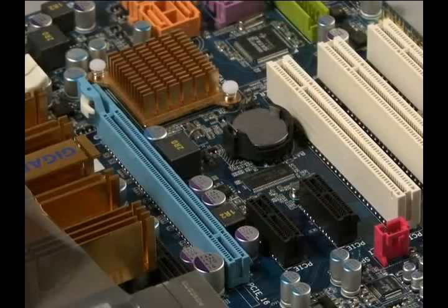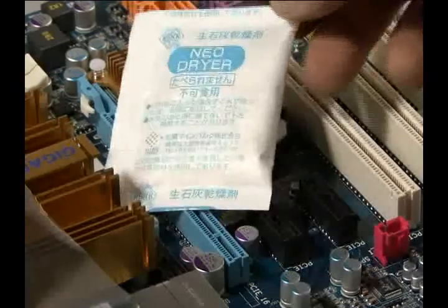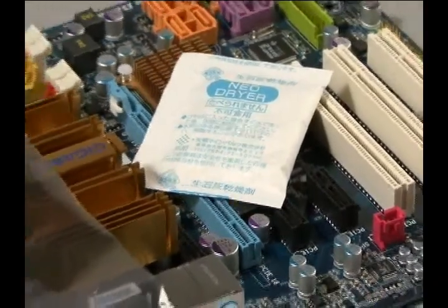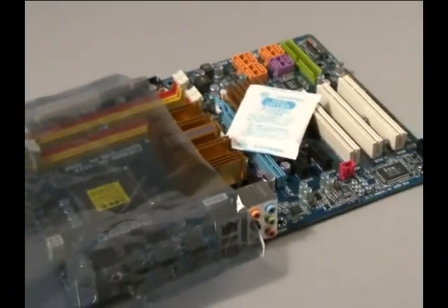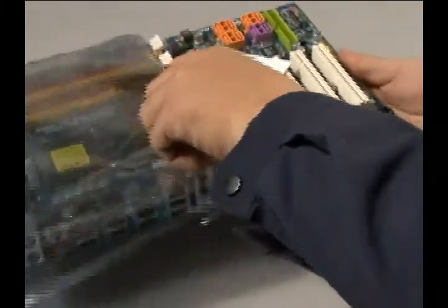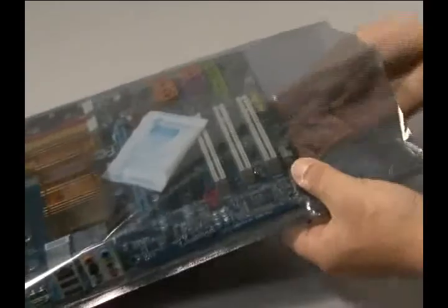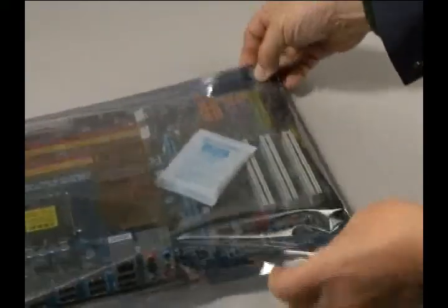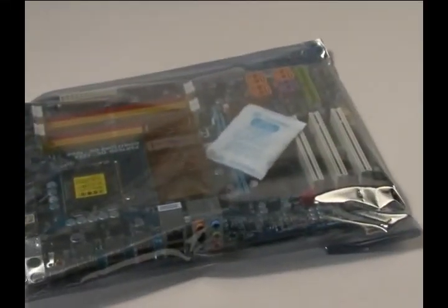A spare electronic circuit board is provided on board ships in case the board in use breaks. This spare electronic circuit board must be placed in a cool place to ensure that it can be used over an extended period of time. However, the electronic circuit board may become rusty if this cool place is humid. To prevent rusting, an electronic circuit board can be stored in a plastic bag, along with a dehumidifying agent.